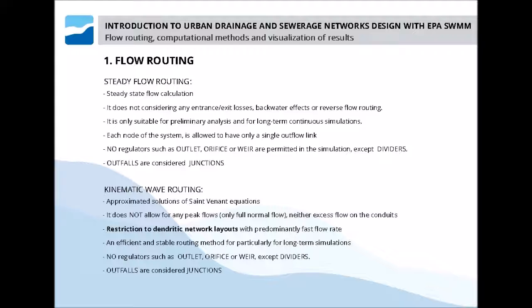The software can use 3 different computational methods: steady flow routing, kinematic wave routing, and dynamic wave routing. Which are the main differences amongst the 3 methods? Well, to start, we can imagine that the steady flow routing is rather a simplified method of calculation. Steady flow routing does not generate any temporary delay, and it does not consider any entrance or exit losses, backwater effects, or reverse flow routing.